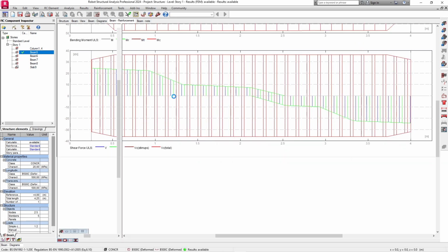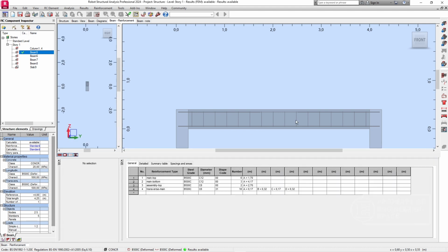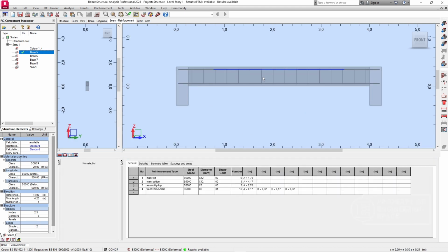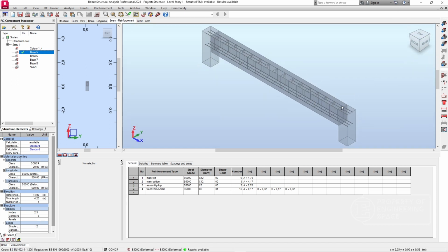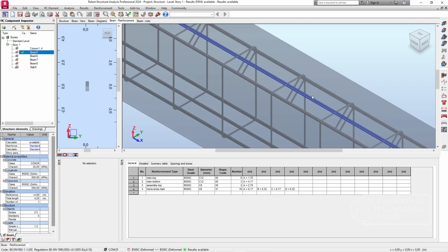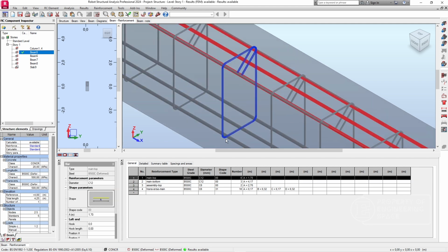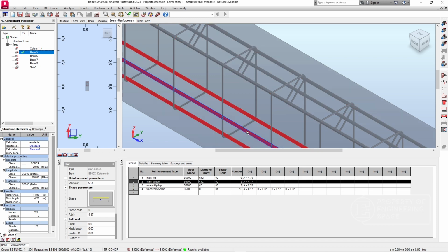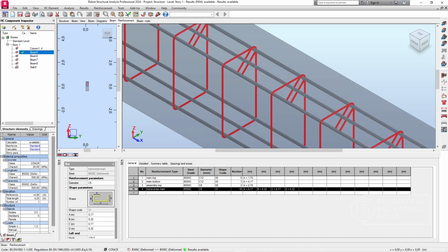If you want to see the reinforcement that we need, you're gonna see these figures using the steel grade B500C standard. We need 12 millimeter and 8 millimeter bars here, and as you can see here, in the center of the bar it needs 12.